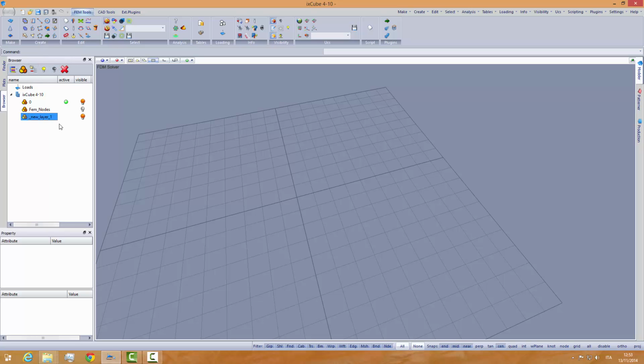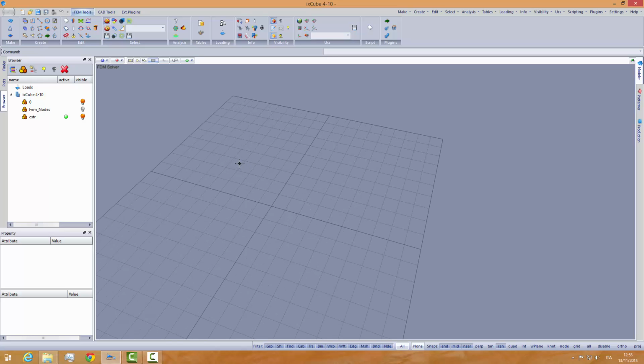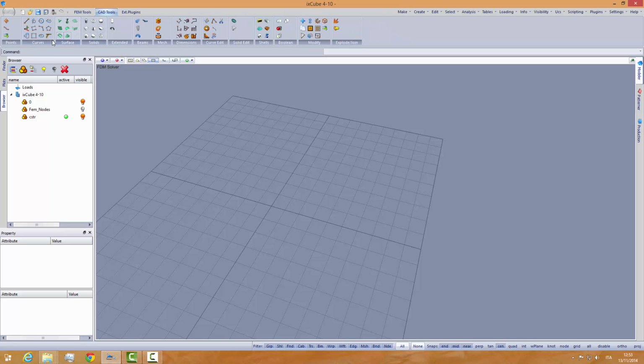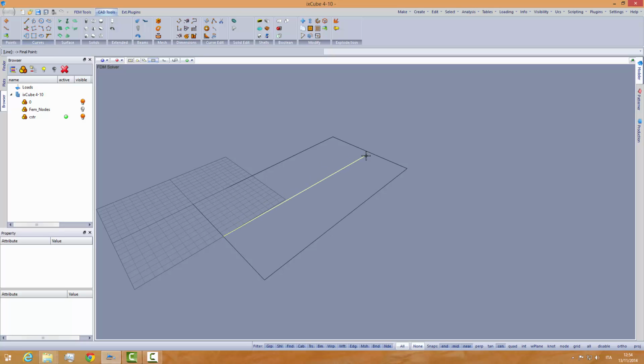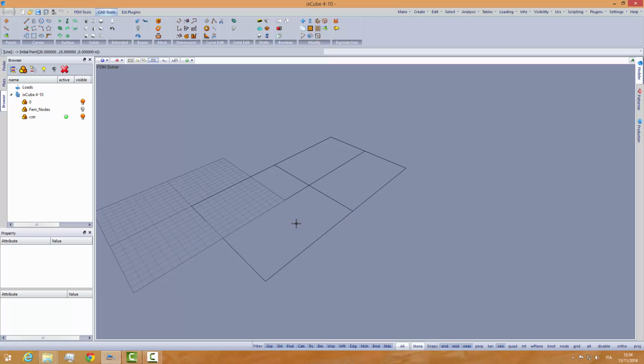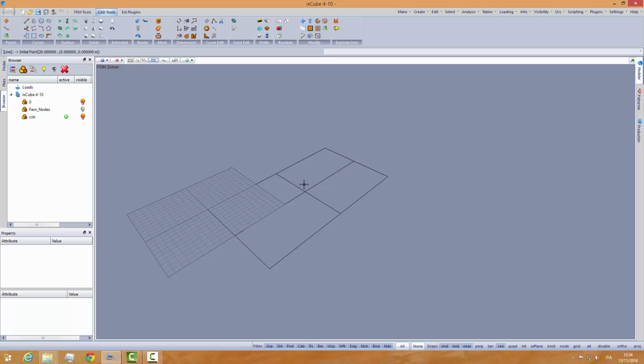First thing, I will create a new layer and name it construction layer, and let's draw in plan. Well, let's say that one module is about 20 by 30 meters. So I will create a rectangle by corners, starting at the origin, and then relative 20 meters wide and 30 meters long. So this is my plan. Let's draw a middle line, like that, and a middle line here. So 30 meters by 20 meters.